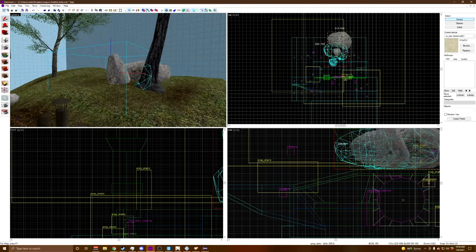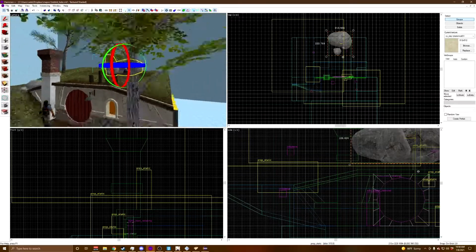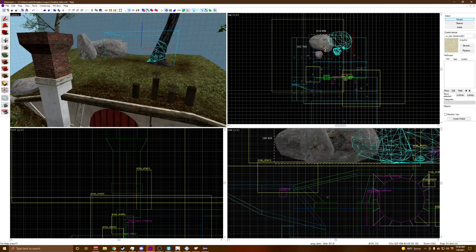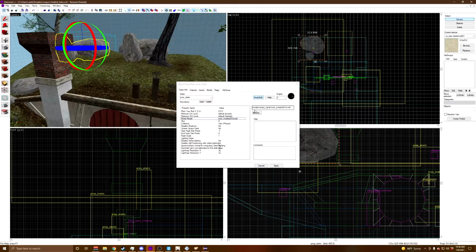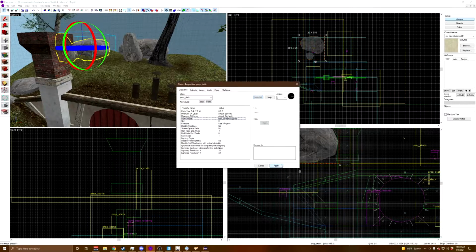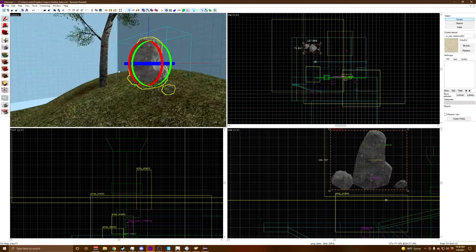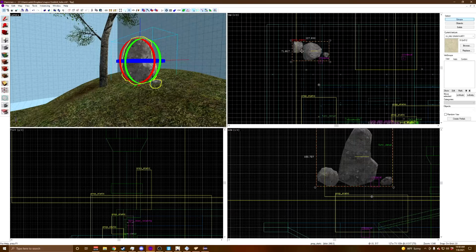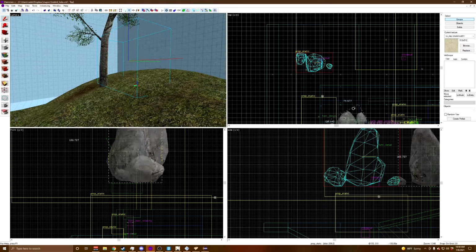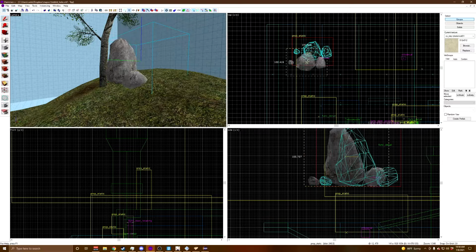If you're trying to place a static prop, for example, in your level, and you boot up the game and you notice that the prop doesn't actually spawn in-game, it's most likely that the model you chose isn't compatible with that prop type. For example, a soda can is not compatible with prop_static. You can get around this by going back to the prop in Hammer and changing its entity type to prop_dynamic_override. This will essentially force it to act like a static prop, and since the models that you'd use this entity for don't have any animations, the only thing that those models will do is sit there and look pretty, just like your standard static prop.